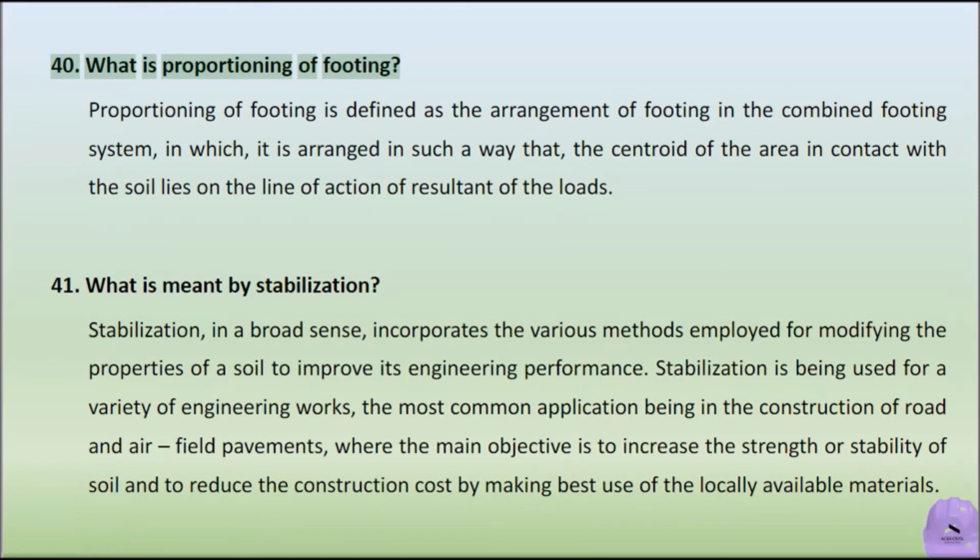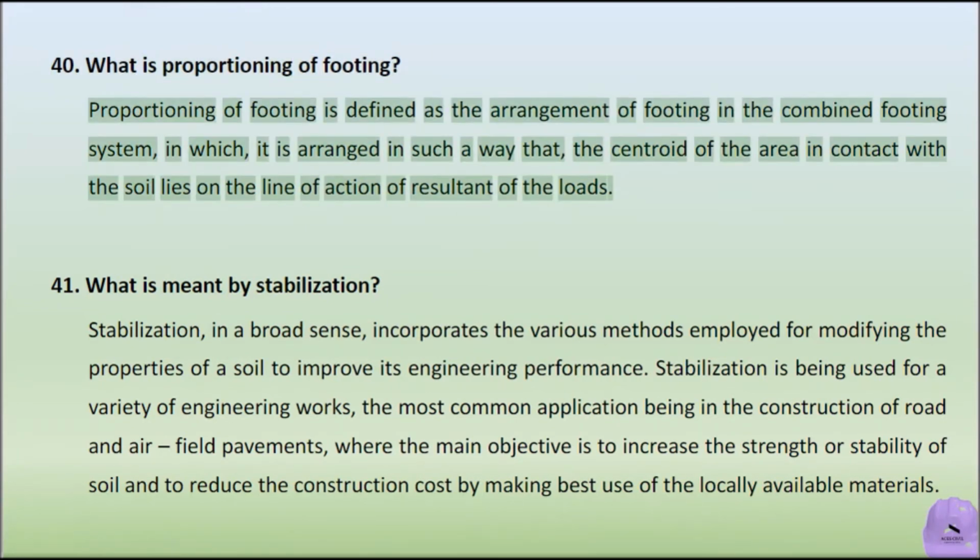What is proportioning of footing? Proportioning of footing is defined as the arrangement of footing in the combined footing system, in which it is arranged in such a way that the centroid of the area in contact with the soil lies on the line of action of the resultant of the loads.